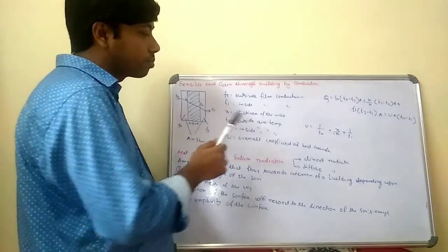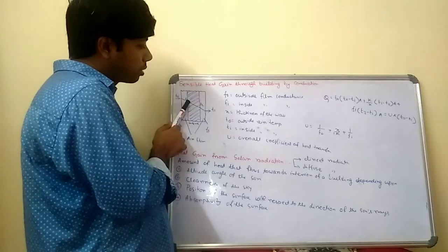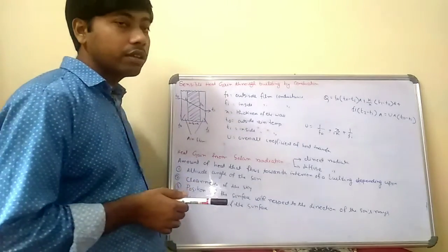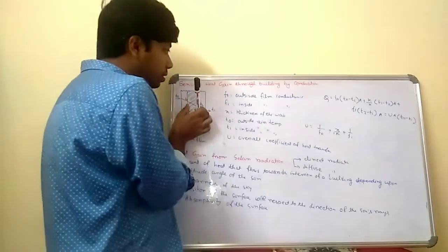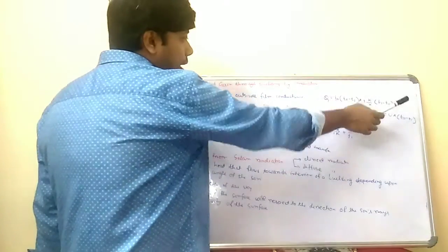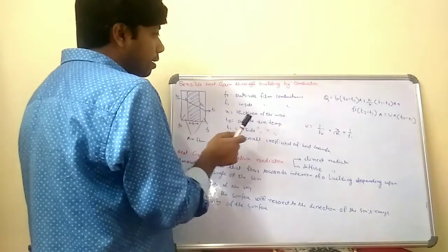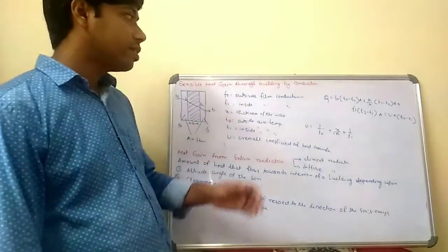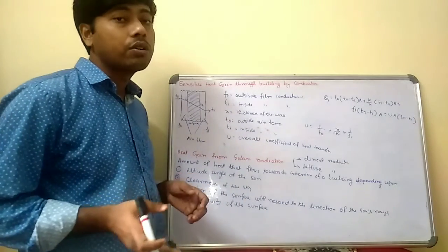So when heat is transferred from the outside wall temperature to the inside wall temperature, it obviously follows Q equals K into A into dt by dx. That will be K by X into T1 minus T2, the temperature difference across the wall, where A is the area of the wall. Plus Fi, the inside wall conductance, into T2 minus Ti, into A. This is equal to U into A into T0 minus Ti, where U is the overall heat transfer coefficient.